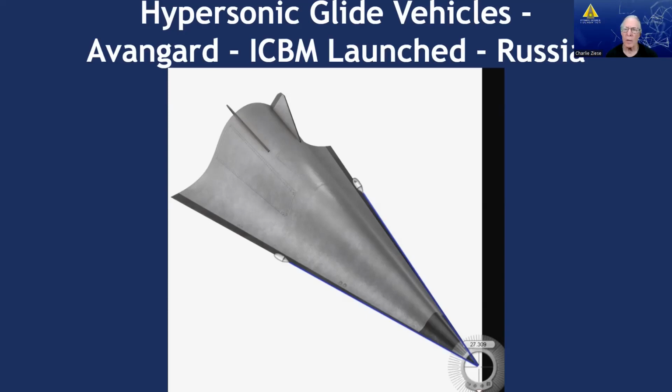Now, if we go back and think about that equation on drag force that we looked at earlier, you know that the drag force is a function of the square of the velocity. So the importance of geometry in minimizing drag is critical to keeping these planes flying and also from burning up in the atmosphere. Because if the geometry isn't right, there's going to be a tremendous amount of heat buildup on the craft. Now, that can be mitigated through geometry, and it also can be mitigated by advanced metallurgy and material science.